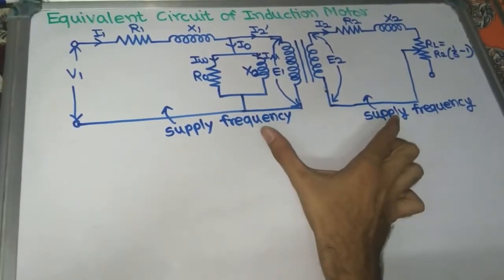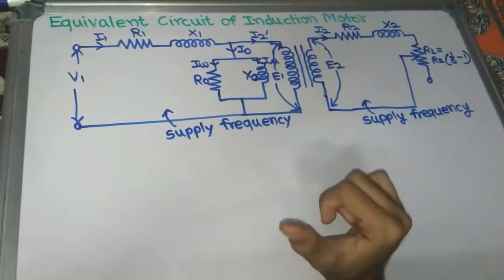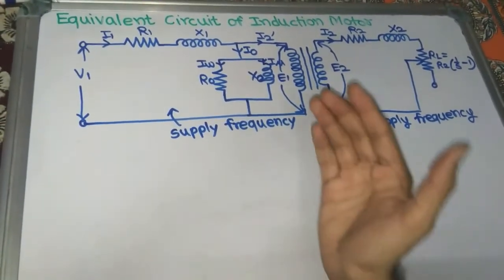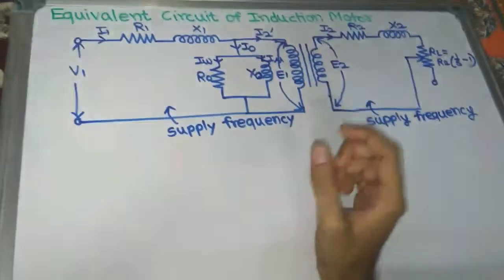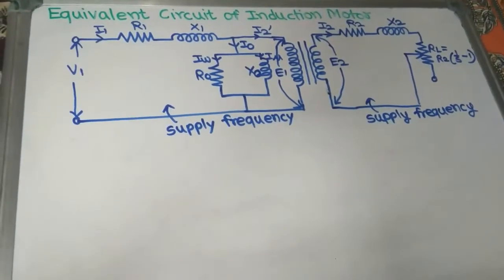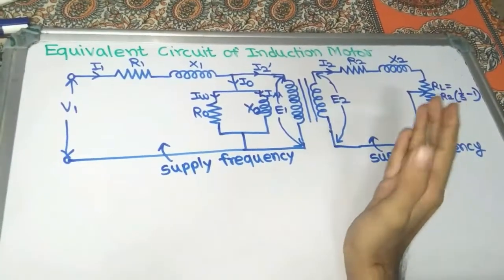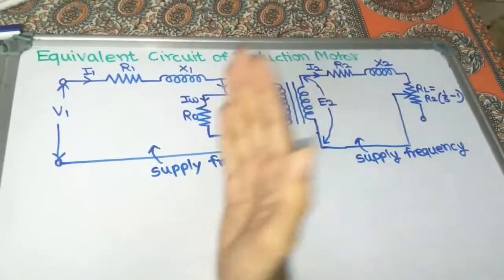And supply frequency to both stator and rotor is now equal. So by making the supply frequency equal, we can say that the three-phase induction motor may act as a generalized transformer. Now can we draw the equivalent circuit of three-phase induction motor referred to stator?